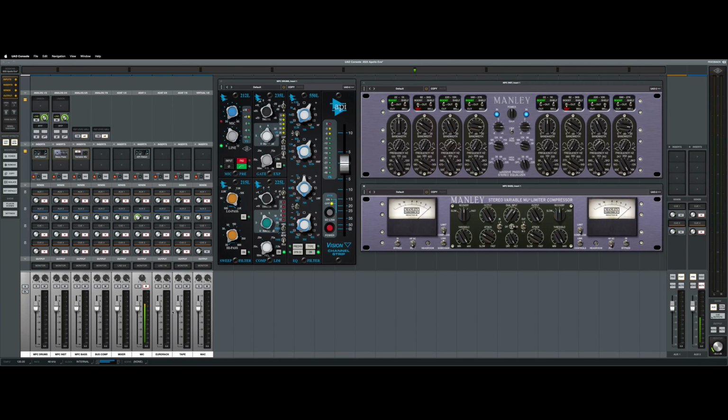You'll notice that I've got no other processing other than the voice here. So the Eurorack has no processing on, normally, because if I want to process it, I'll process it analog. So I'll come out like I have here, where it says 7 and 8. This means the Eurorack goes out to the mixer. I can mess around with the mixer settings, a bit of EQ, and then drive that signal out of the mixer into the bus compressor, and then record the clean signal, the mixer signal, and the bus compressor signal completely separate from each other, but simultaneously.